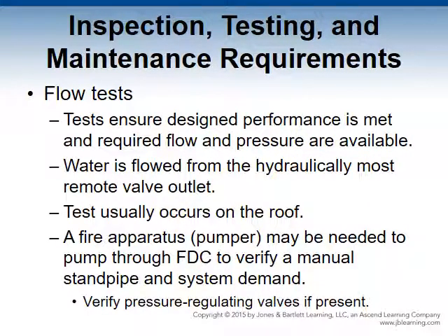Flow test. These tests ensure the following: that the system delivers the design level of performance, and that required flow and pressures are available. Water is flowed from the hydraulically most remote hose valve outlet. A pitot tube and riser gauge help determine the flow and pressure readings.